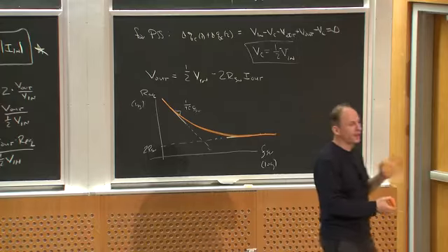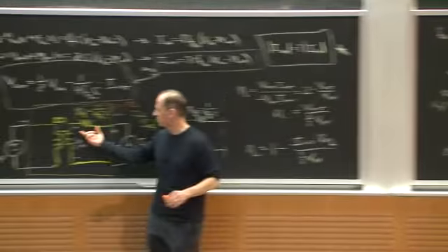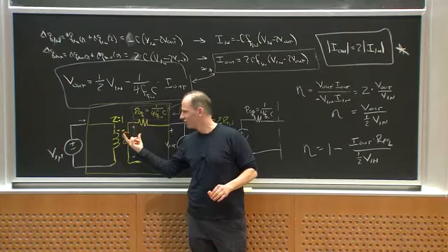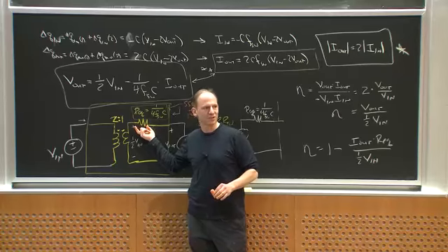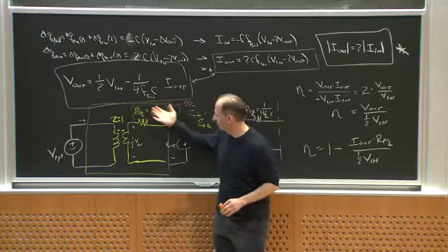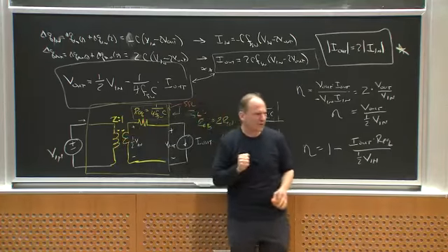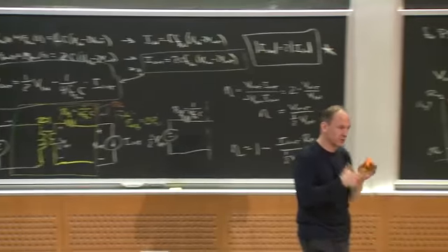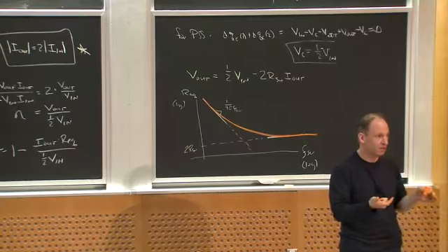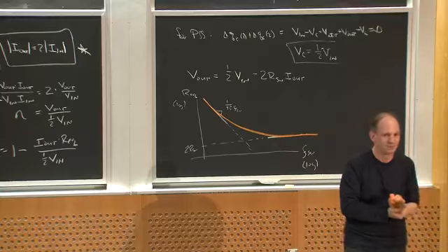Well, yes, but only through the action of essentially what this resistance is. For any given converter, there's a duty ratio that'll give you the lowest output resistance. Even in the slow switching limit, you can change the conversion ratio, but you're doing it through a resistive drop. It's like you have an ideal transformer and then a linear regulator kind of thing. So you can always use switching frequency, and in the fast switching limit duty ratio, to change the conversion ratio, but not in a perfectly efficient sense.